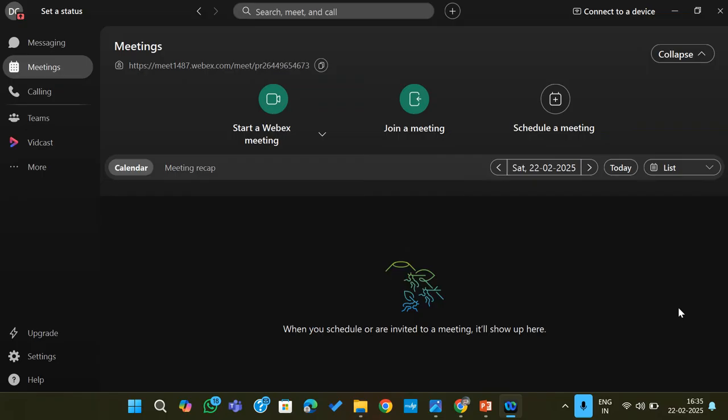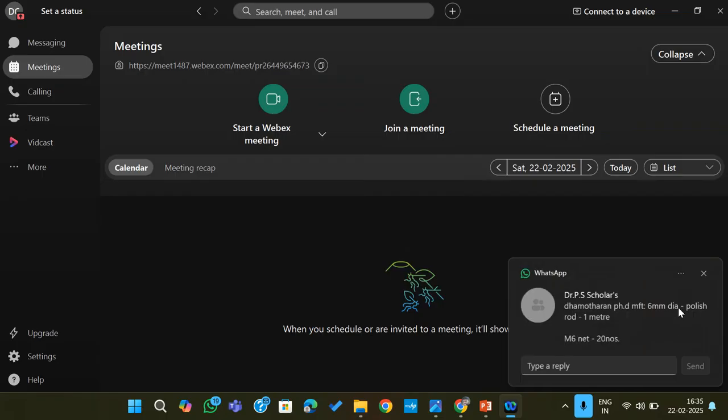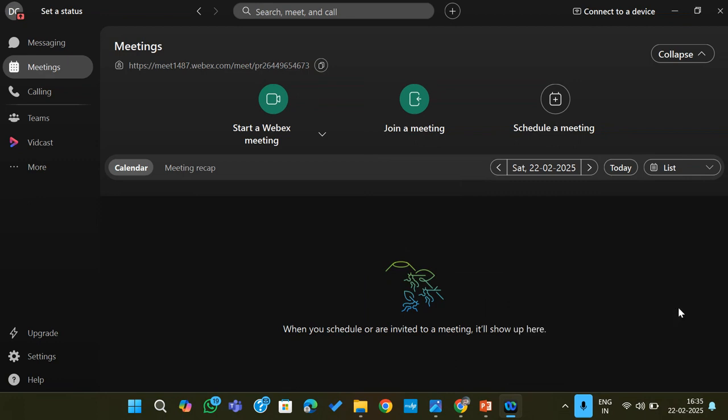Yes, Professor. One more doubt. In rotary friction welding, we are doing cylindrical kinds of jobs. Other than friction welding, what method was previously used to join two cylindrical components, Professor? Cylindrical components can also be joined by fusion welding techniques like GMAW and GTAW. It is possible, but the joint quality is good when we prefer the rotary friction welding technique.